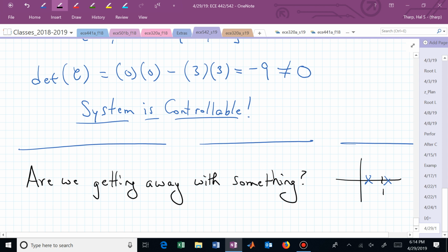Yes, if my drawing is somewhat right. Whoops, that was supposed to be red. My root locus would look like that, wouldn't it? Where are your closed loop poles? Are they anywhere inside the unit circle? They're only on the root locus, only on those red lines.